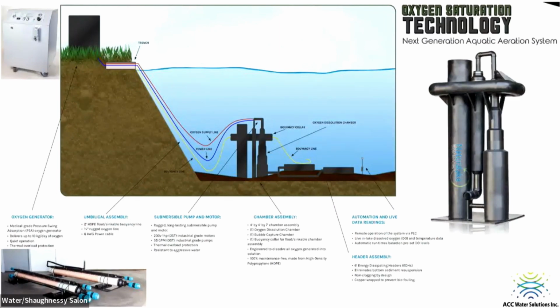It's got a species cone-like device in there. The advantage of this over the big old traditional species cones is you can float that right into the middle of the water. It's got that collar on it. That collar, we fill it with air. We float it, both of the intake and the outtake canisters, which are the same ones I showed you the picture of before. They have flotation devices on them as well. You float it to exactly where you want it in the water body. Kick on your trash pump, fill those with water, and it sinks to the bottom exactly where you want to have it. If you need to do maintenance on it, you plug in a compressor, and you float it up to the top. All of the maintenance can be done from the surface.